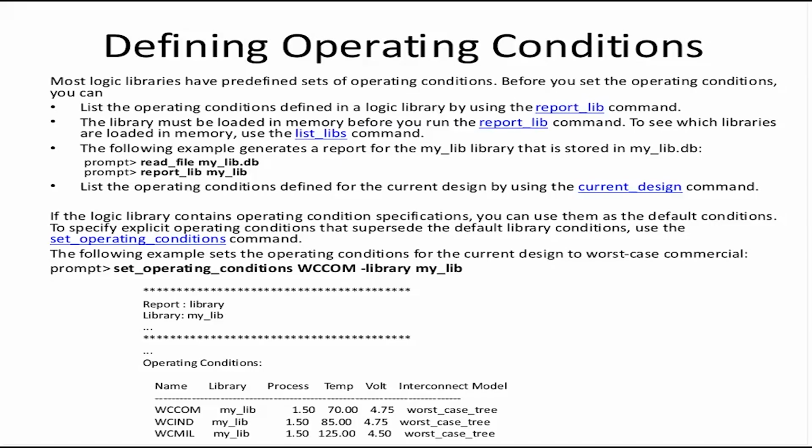So when we talk about operating condition, we should synthesize at a slow corner, because at a slow process corner, the delays will be more. So it will be a limiting factor in terms of performance. Again, we should choose a higher temperature in most of the technologies. I say most because some technologies have a negative temperature effect, where when the temperature is less, the delays are more. But let's not worry about that. In most of the technologies, higher temperature means higher delay. So we should choose a higher temperature.